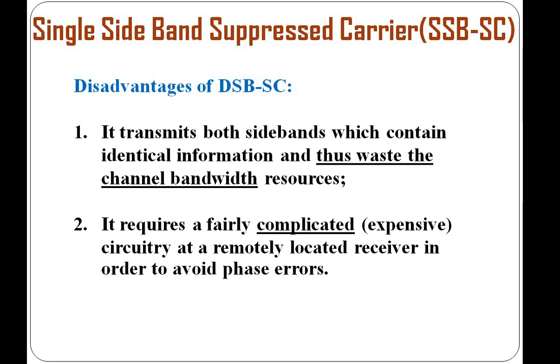So what was the Hilbert transform? Unlike other transforms like the Fourier transform or Laplace transform, we are not going to change the domain of the signal, from time domain to frequency domain or vice versa. The domain will be the same as the time domain, but only the phase will be changed.